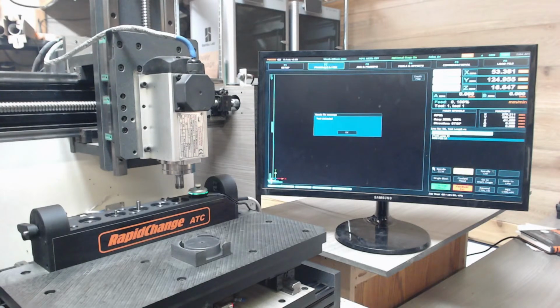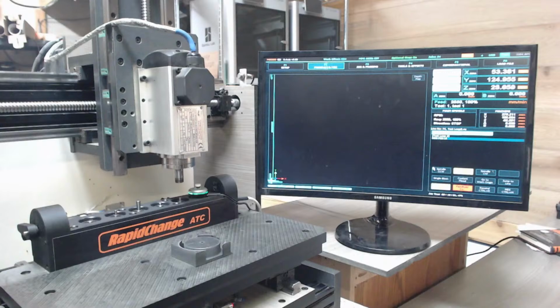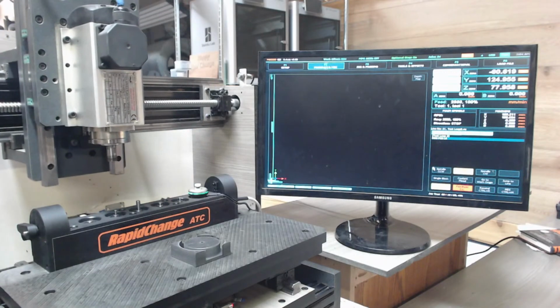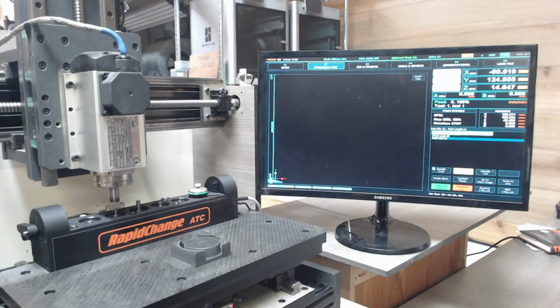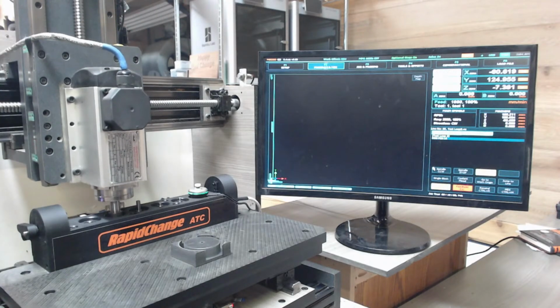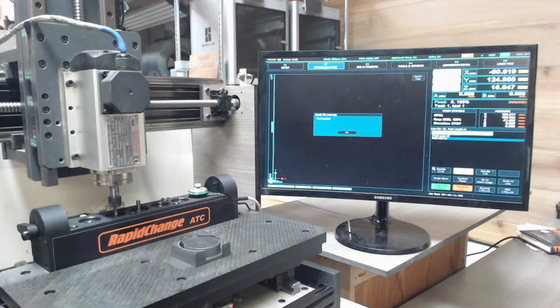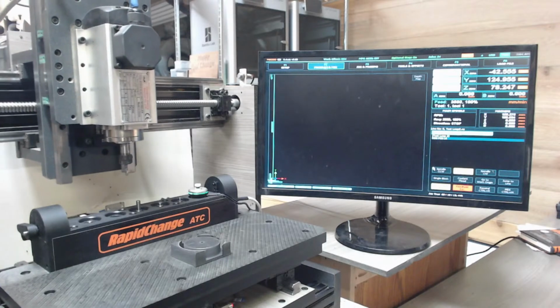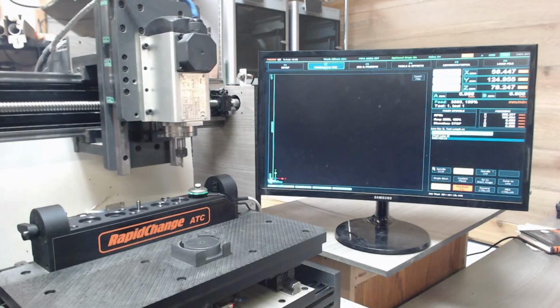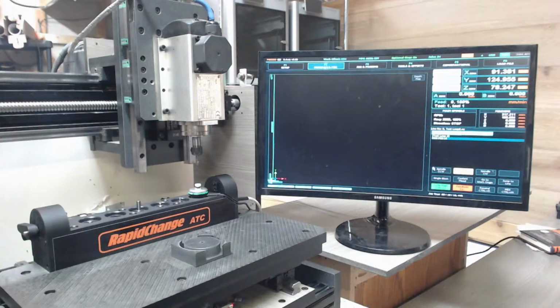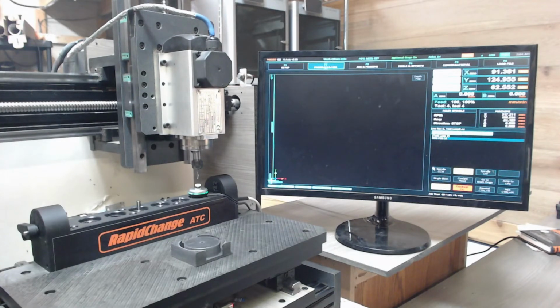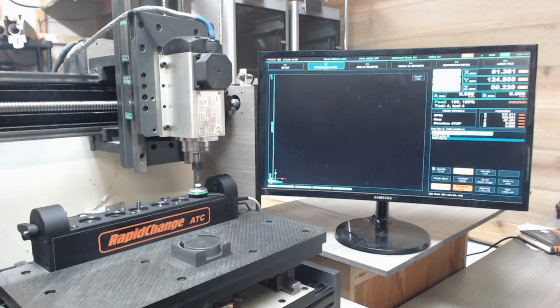What material are the grayish plates made of? No, it's not aluminum. It is natural paper phenolic, which is layers of kraft paper impregnated with phenolic resin, and I don't know, they compress it at like 50 tons or something. But it's super rigid. It machines really well. It's a little hard on the cutters, but super rigid, way better than aluminum.